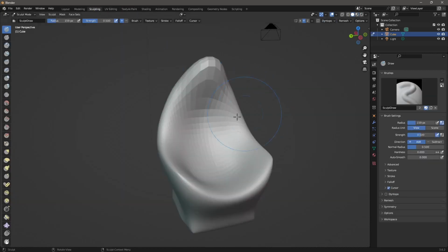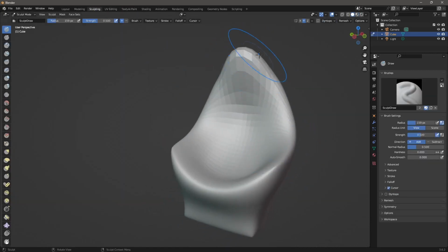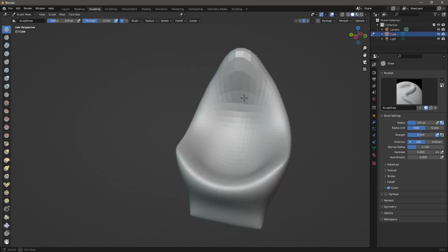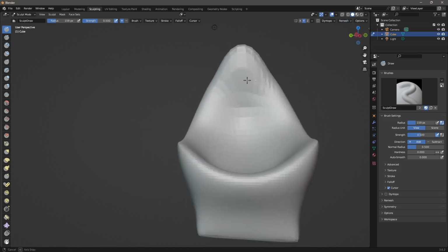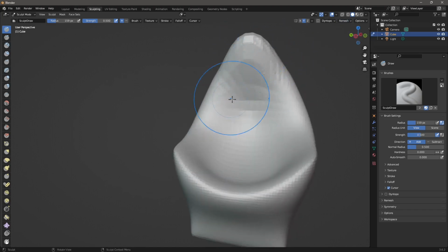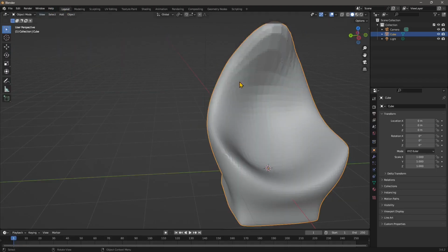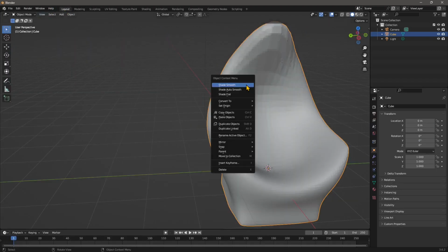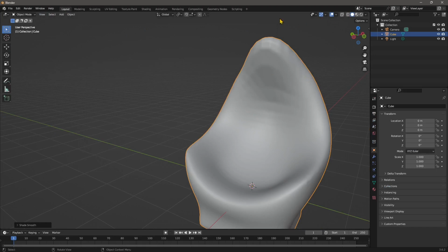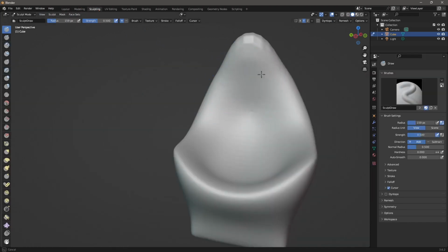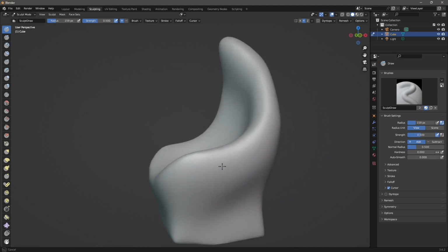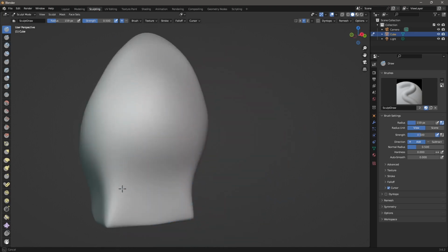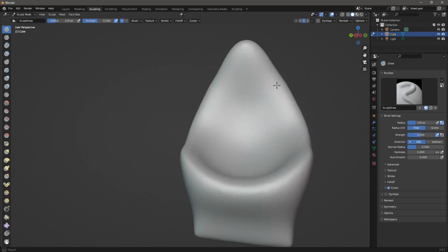Now if we go back to sculpting and we want to fix these stretched polygons, well, there are many ways, but a quick way is to remesh. So if I remesh again, you can see now this is more irregular. And don't worry about the faces. If you want something smoother, you right click in object mode and do shade smooth. So you have a nice and smooth geometry. And then we can also smooth with the smooth tool. Now you can see that everything looks nice and smoother than before, but it doesn't have a regular structure.